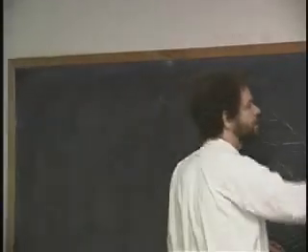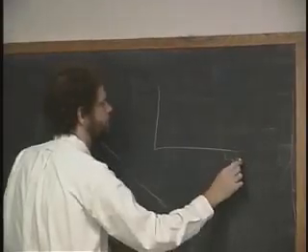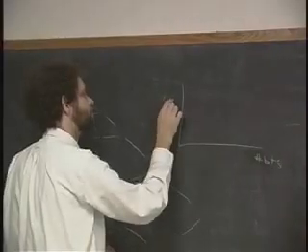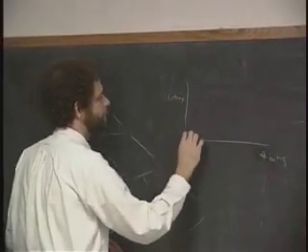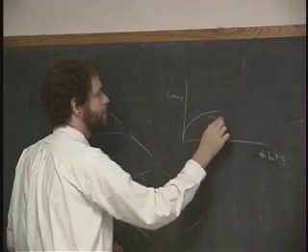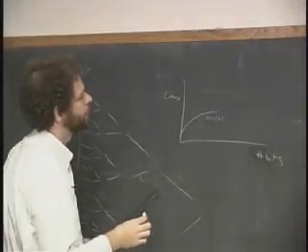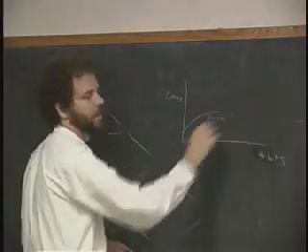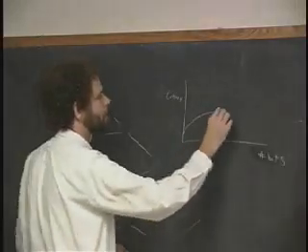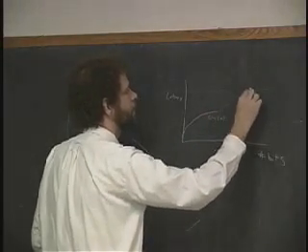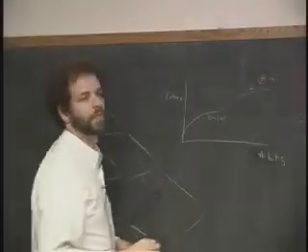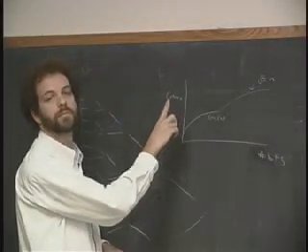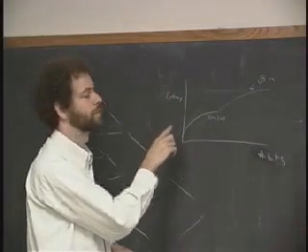And so if I were to plot latency versus number of bits, at the beginning I'm going to have a curve which looks like log n. But later on, what does the cube root look like? Is it steeper than log n? Is it flatter than log n? Or does it go up more than log n? Steeper. So it looks steeper, right? So there's another curve here, and this is the cube root of n. But the important thing is as the number of bits goes up, the latency goes up. And there's a fundamental reason why that needs to be true.